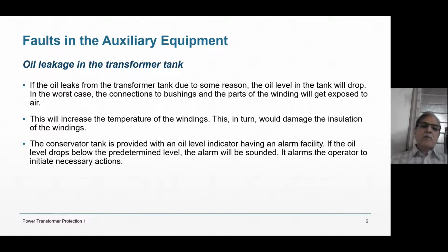Silica gel absorbs the moisture, and its color is usually blue, but when it converts into pink, it is full of moisture now. So you have to remove that silica gel and expose it into atmosphere in heat, so that once again the moisture is evaporated and you can fill up once again.